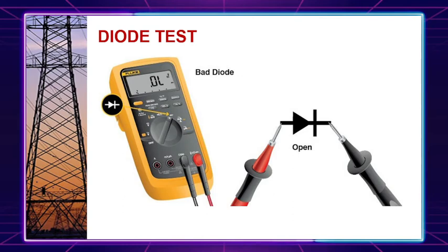Okay, a good diode should produce a small voltage between the test leads, enough to forward bias a diode junction. It should be 0.5 to 0.8 volts based on its voltage drop. If you're using a digital multimeter, a good diode should display OL, which indicates very high resistance.